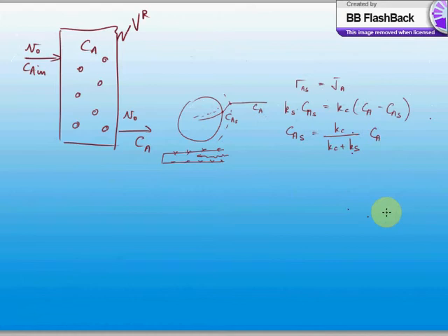And if you recall the derivation for the concentration gradient across the particle, namely to give us the internal effectiveness factor, then you can see how to correct for CAS. So remember that the average concentration inside the particle is equal to the internal effectiveness factor times the concentration on the surface of that particle. So this parameter we derived in terms of a mass balance across that particle.